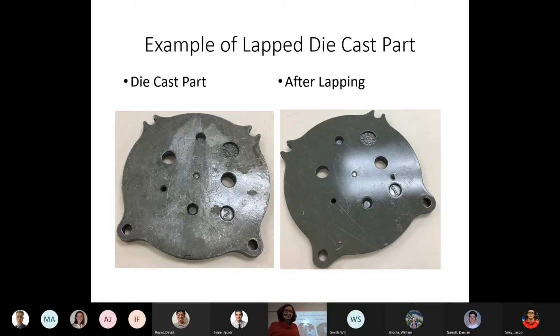Okay, so these are the two abrasive finishing processes that we've looked at. There are a few more, like super polishing and a couple others. But in general, if we go with a smooth, small grit abrasive, we can get smoother surfaces.